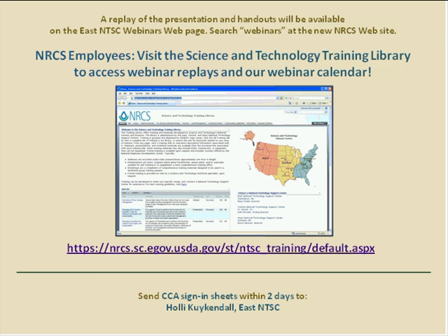I don't think you're going to have that quick of a response. Your drainage isn't happening like it's not going to be like the flow in a grassed waterway during a 10-year, 24-hour storm. So I think that if you raise these flashboards up and then immediately start land applying your manure, you're going to be okay. But I'd like to hear what you have to say, too.